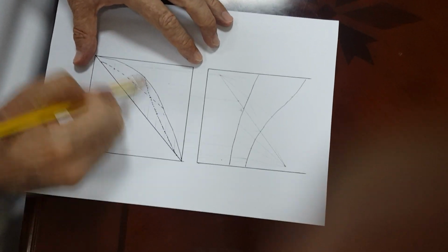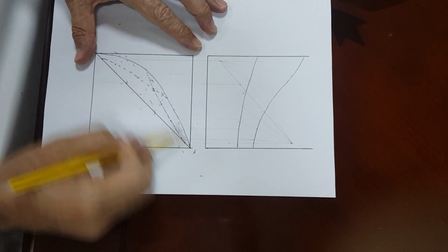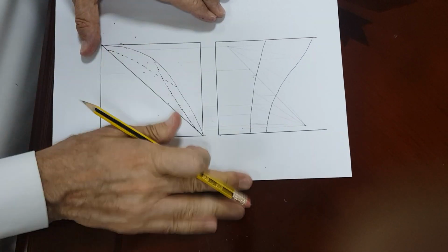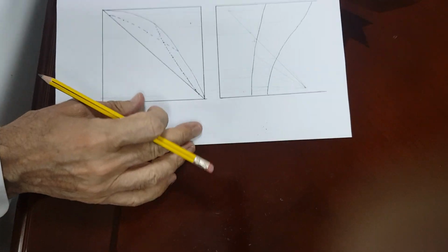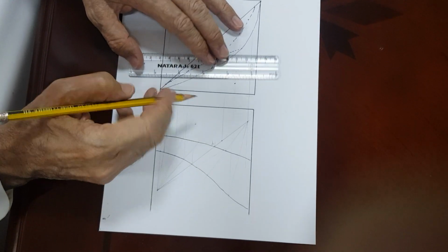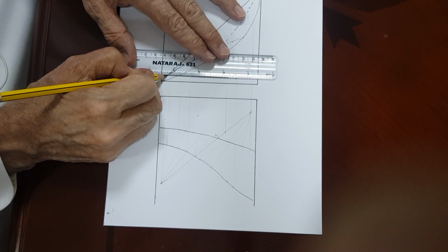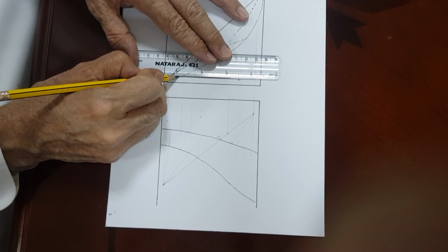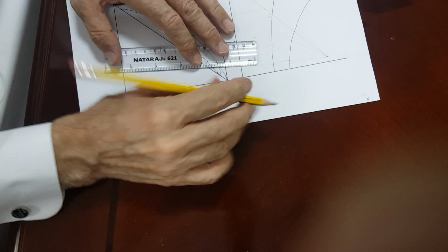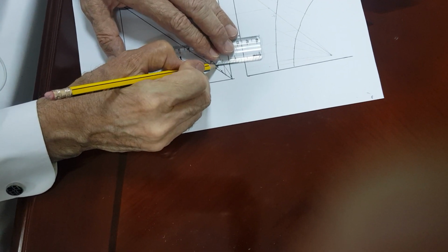So what you do is, once you have the two nonlinear operating lines, you can use a method similar to McCabe-Thiele. So all you do is you start at XW or ZW, and you just draw your stages, horizontal, then vertical.